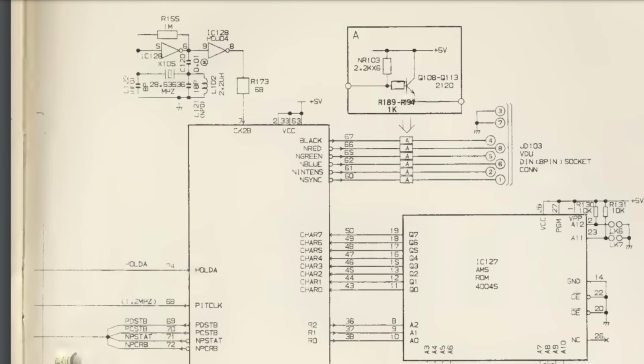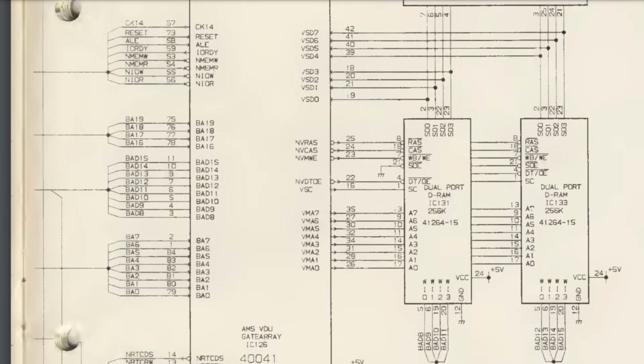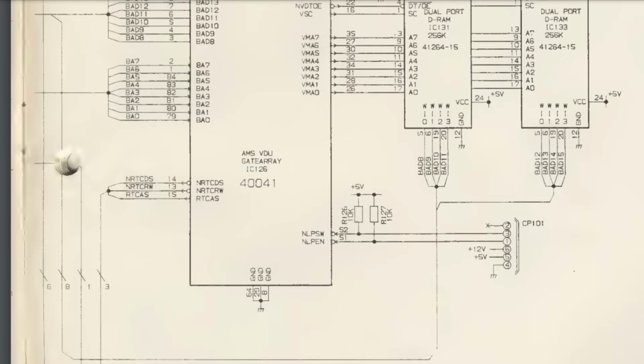So that's not too bad. It's not as good as what we had on the PC, but it's pretty good. Now, it's a little bit complicated to do this. If the CPU is running some other instruction, the interrupt has to wait for that to finish. But you can halt the CPU and just have it sit there waiting for an interrupt. So I'm going to have to set it up so that just before the interrupt fires, the CPU goes into halt and waits for the interrupt to fire, so there's nothing happening when the interrupt comes. And I think that should enable us to get pretty close to pixel perfect, and we'll see how that goes.